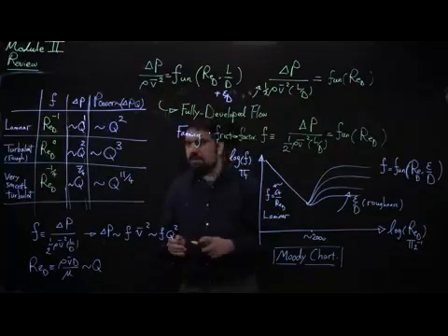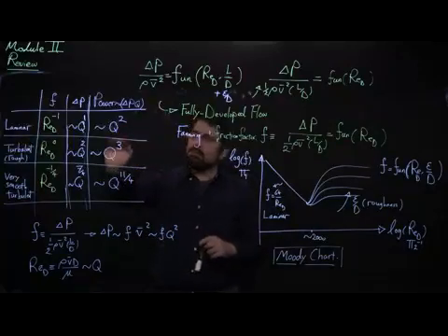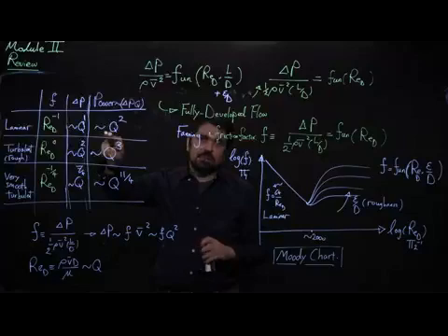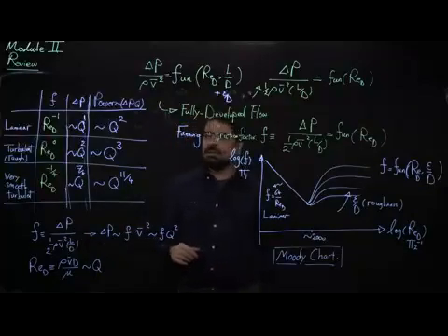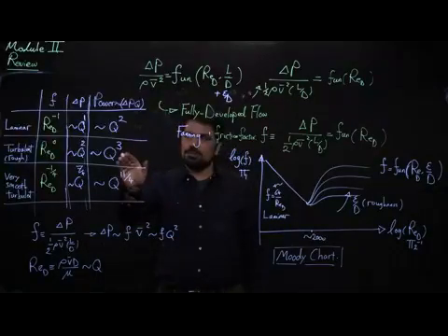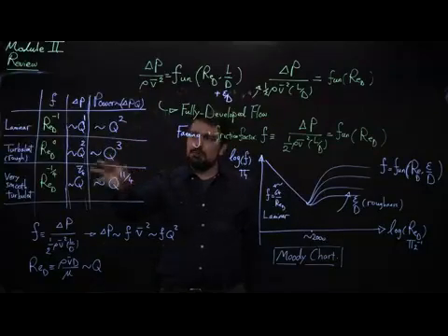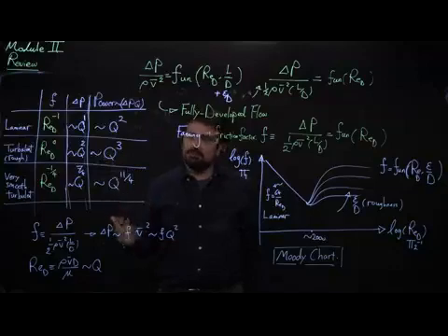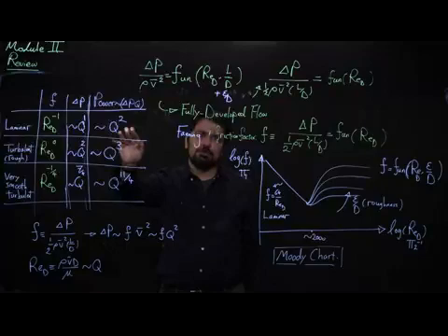Now you have a clear idea why people say it's good to keep the flow in the laminar regime. Because when you are in the laminar regime, as you increase the volumetric flow rate, the power that your pump is required to maintain that flow rate is not going to increase in a Q to the power of 3 manner. It's going to increase in a Q to the power of 2 manner, which is much better than the turbulent regime. If in the turbulent regime you increase the flow rate by a factor of 2, you need 8 times more power. But here you only need 4 times more power.